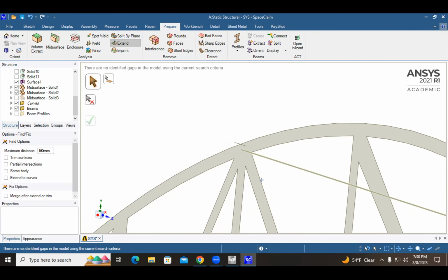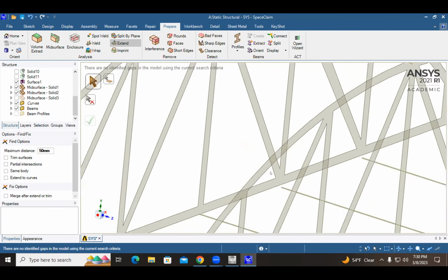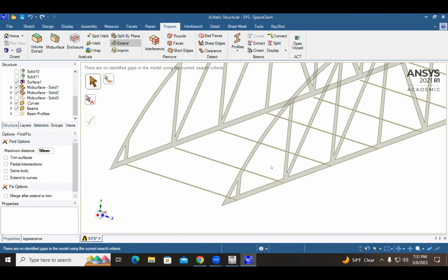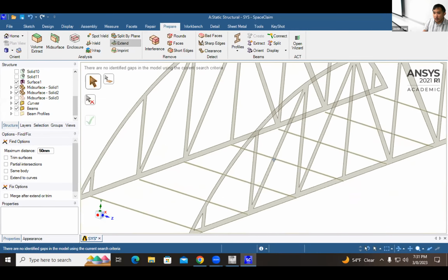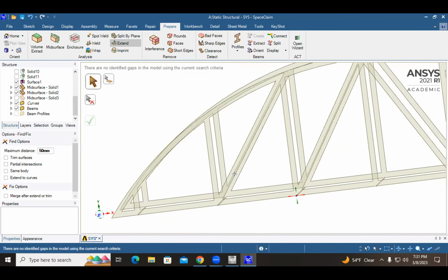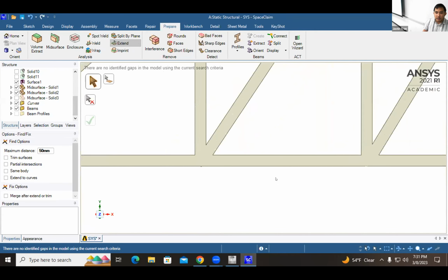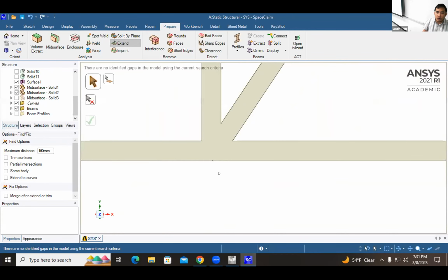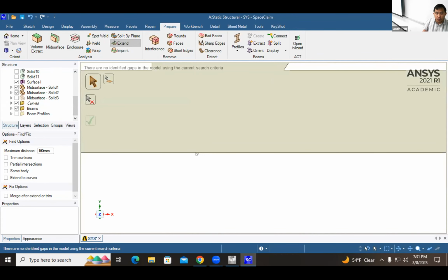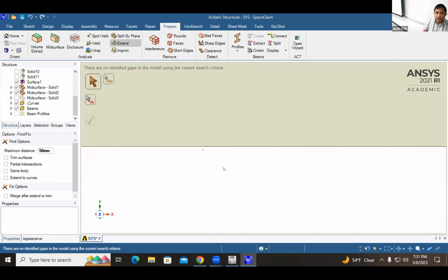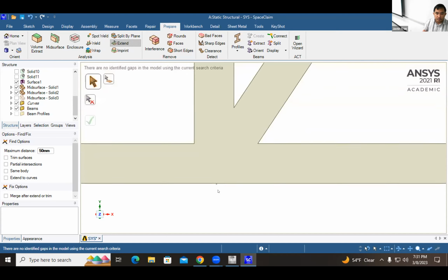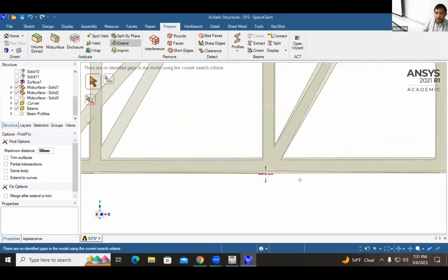And on the bottom beams, if they didn't give me an option to click to extend, is that fine? Yeah, so we're going to fix that right now. That's what I've been saying for the last few minutes. Basically the reason they're not able to extend is because the beams are a little bit too far down. The beam is now just a one-dimensional object, right? And so in order for it to connect, we need to move this up a little bit. I don't know if you can see there's a little bit of a gap between this beam right here, this dot, and the bottom of the bridge, which is right here. Yeah, thank you. That's exactly what we're going to be doing.